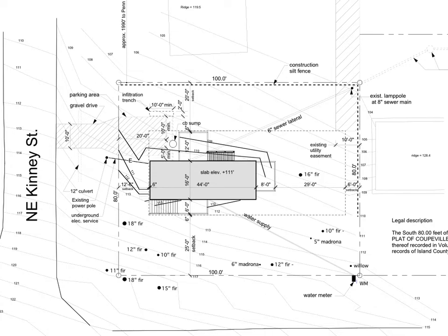This is a finished site plan, which just shows all of that information, some existing information, but then also the changes. So the house footprint has been put on, the setbacks have been marked on it, an easement from the neighbor's property is marked. The proposed new utilities, water line coming in and a sewer line going out, have been marked on there. Potential driveway has been mapped out. So all the information about what's going on that site.